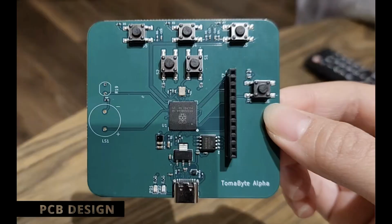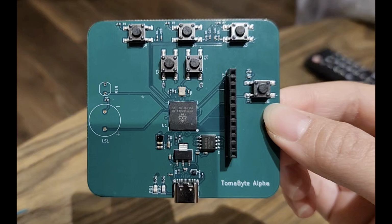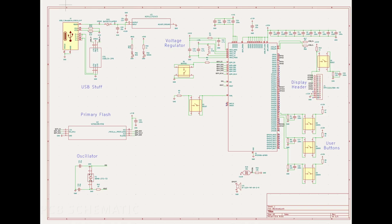The PCB is designed to be small and easy to play. The dimensions of the design are 2.6 inches by 2.85 inches to make sure that the Tamagotchi can be held easily. The design of the hardware for the RP2350 consisted of 4 main parts: the voltage regulator, flash memory, crystal oscillator, and the USB for input power.